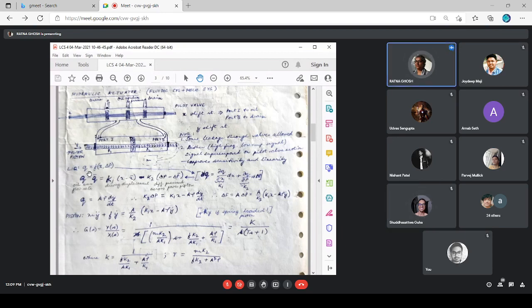So now the point is, this liquid mass flow rate, everything is driven by this oil flow into port 1 and the oil drain out of port 2. Okay. Yes, ma'am. So our concern is essentially this oil mass flow rate. This decides how much this power piston will move. So what all does this oil mass flow rate depend on? Naturally, it depends on the initial movement that is given to this pilot valve, X.